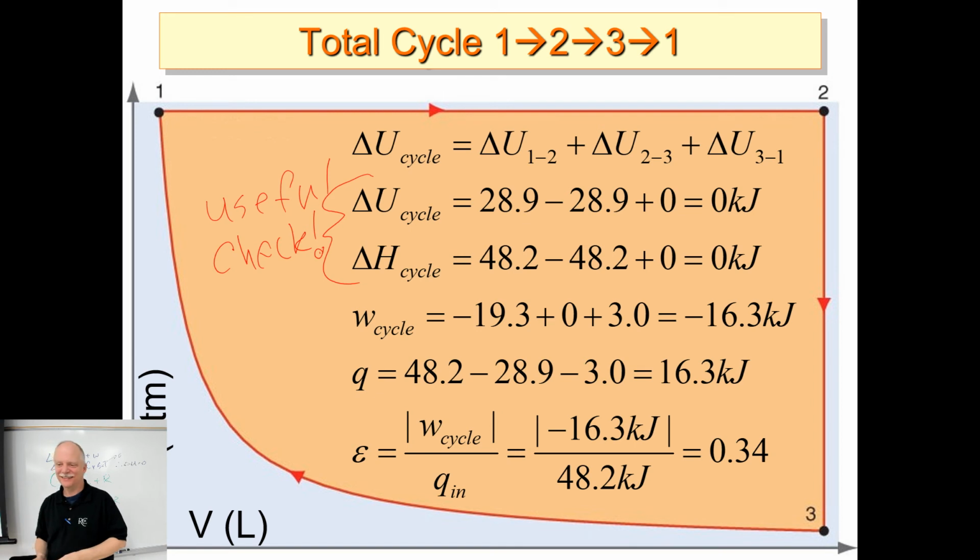Towards the end, you're going to want us to work through all that to get the efficiency, the percent? Yeah, so when you get to the efficiency, you're done. You've got the whole cycle, you know what every leg is doing, you've got the net amount of work you're going to get out of it, and then you've got the efficiency of that cycle. Now we'll compare that to a Carnot cycle. A Carnot cycle is the most efficient possible cycle. All 4 legs are reversible. Because reversible processes are smooth, we get the most work out of them, or the most efficient heat and work conversions. We'll look at Carnot cycles next time.